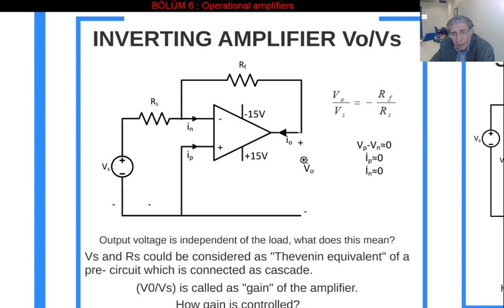It is an amplifier, and the sign of this output voltage is going to be negative. Whatever the sign of your input is, it is going to be multiplied by -1. That's why it is an inverting amplifier. So how are we going to decide whether this is an inverting amplifier or not? This circuit is given to us, and we are saying this is an inverting amplifier. What I could do is calculate that V0 and interpret the mathematical relation that I found for V0.